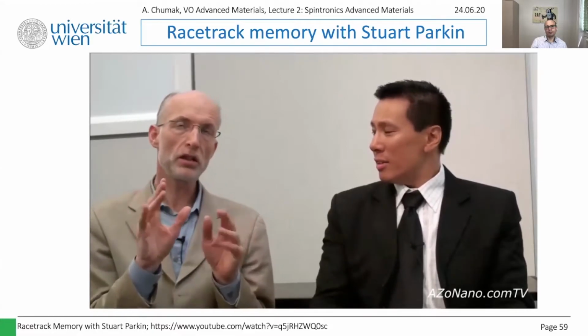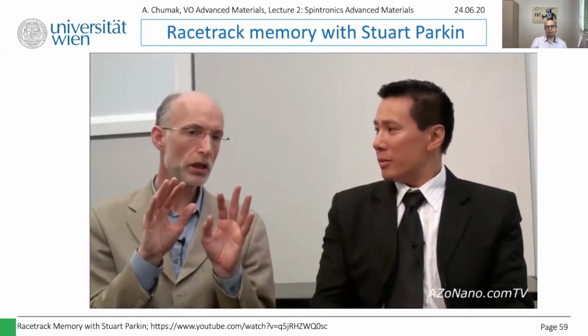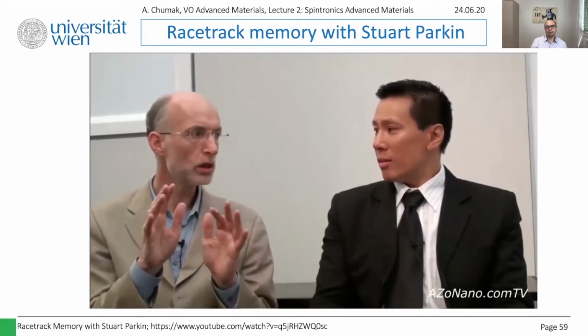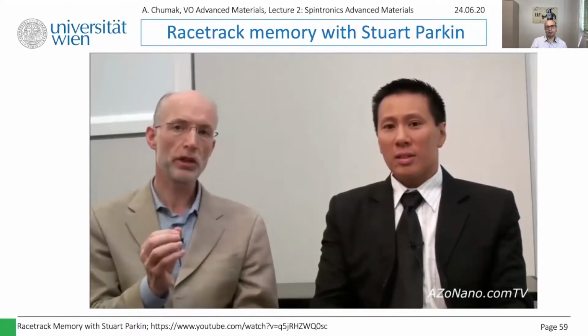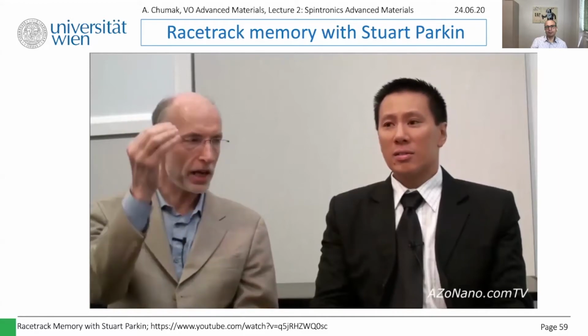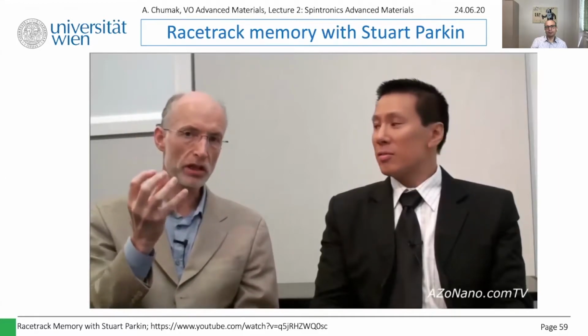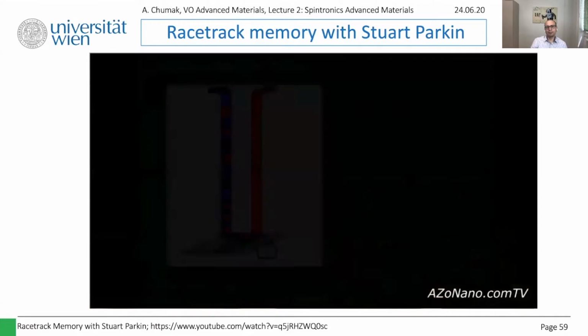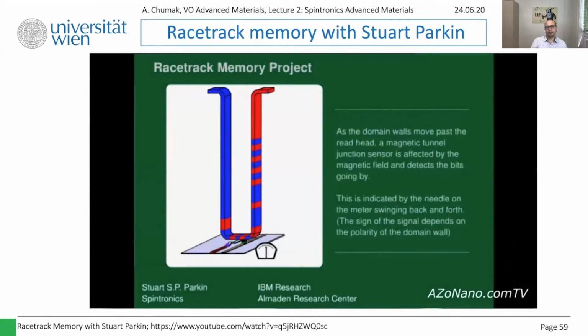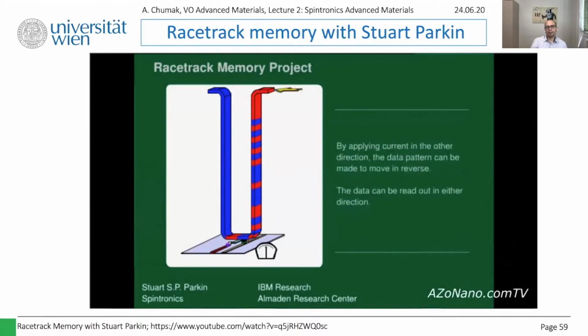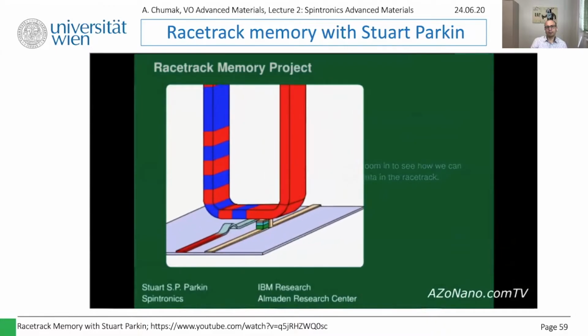Well, the name racetrack is because it's really very different in structure from nearly all conventional solid state memories. The reason we call it racetrack is that we're going to have magnetic nanowires, and the nanowires will contain magnetic regions, like little race cars. We're going to move these race cars up and down these nanowires, which will stand above a silicon wafer. And so in the same area of silicon where today we store a single bit in a conventional solid-state memory, we can store many, many bits by storing them out of the plane of the silicon wafer into the third dimension in these very, very tall magnetic nanowires.